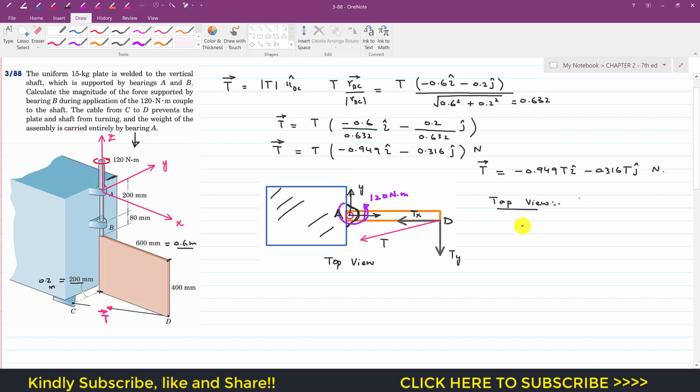So if we apply the summation of moment about point A equals 0 in the top view, and if we assume that the counterclockwise moment is positive, this couple is the counterclockwise moment. So we will write plus 120, and the moment produced by this Tx is 0, so Ty is producing the clockwise moment about that point A. So I will write minus Ty,